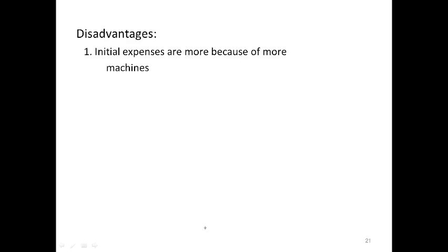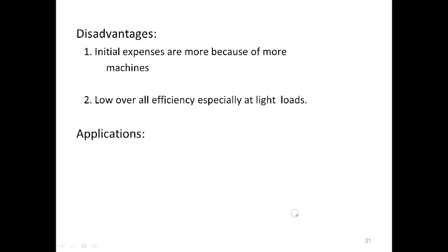Here in the disadvantages, we have to place another MG set, which is expensive, and the overall efficiency is lower. If you run this at light load condition we get low overall efficiency. If we run it for higher loads it is more applicable. The applications are winders and elevators; we are using it for colliery winders and elevators.